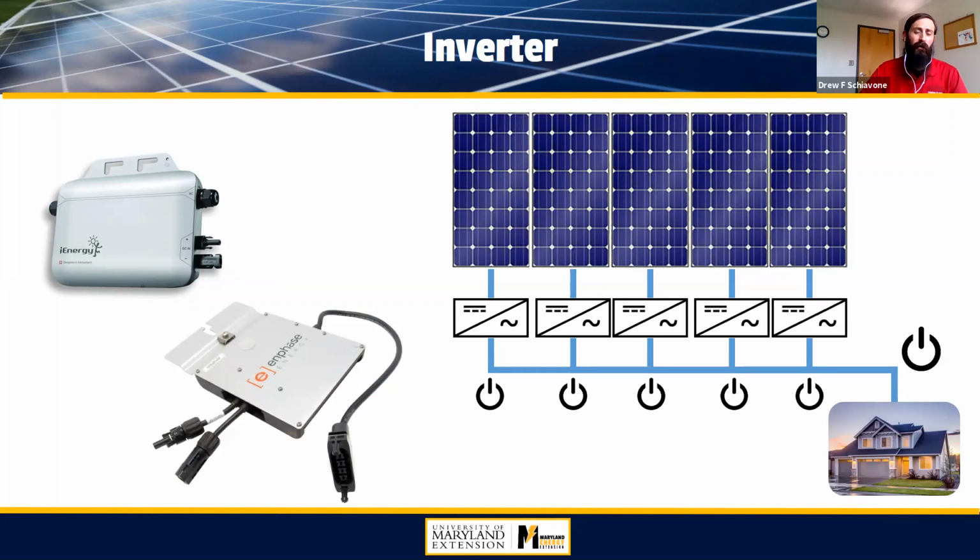Here's what an example of a microinverter would look like. In this case, you have a very small microinverter attached to each module, and that's growing in popularity. I think it's like 40% of the market now is microinverters. In any sense, inverters are a big expense, a big part of your PV expenses, probably around a quarter of the cost of the module itself. So it is a big piece of the puzzle.